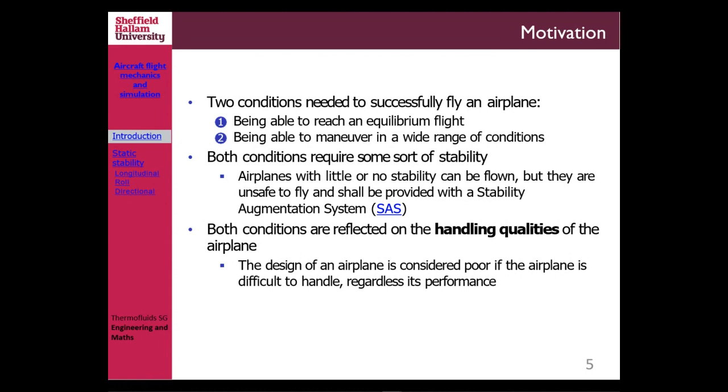But for a conventional aircraft, like the commercial passenger jet aircraft that you are designing, I think there's no question that you have to design a stable aircraft, right? Now, how should an unstable aircraft be flown if it's designed unstable? Obviously, the pilot needs to be helped by a set of computers. That set of computers provides augmented stability to the aircraft.